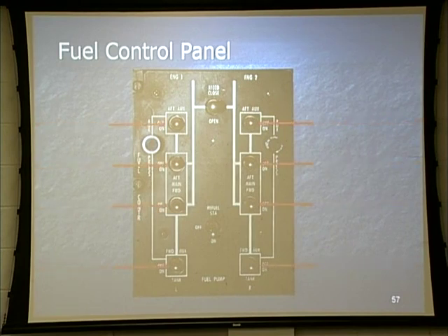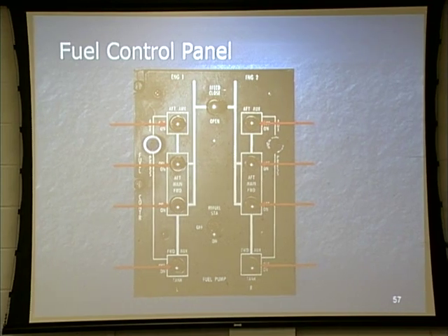As we look at it, again, you've got a pump. You've got a switch for every pump. You've got a 2-position switch, off and on, keeping in mind that it's going to go from the aft position or upper position to forward or down position when you turn it on. It allows you to control the pumps individually, but reality is, when would I have to turn off pumps? Normally it says all fuel switches on, crossfeed closed, right? When would I have to do anything different than that?